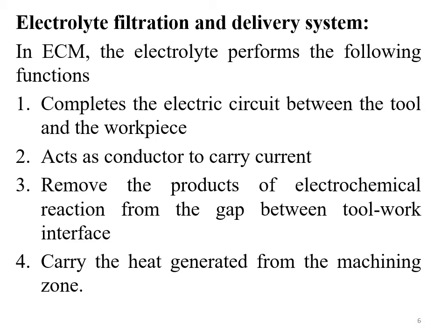That is what we signify as the transport of current, or movement of current. So carrying current is nothing but moving electrons from one location to another. This is possible here only when the electrodes are dipped in an electrolyte solution, and the electrolyte causes the action of carrying the current from one electrode to the other. Further, it removes the products of the electrochemical reaction from the gap between the tool and the workpiece interface.